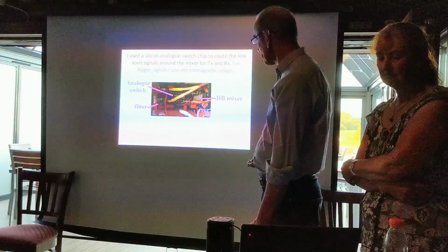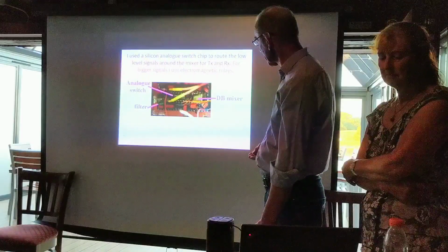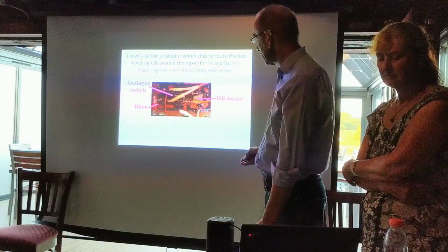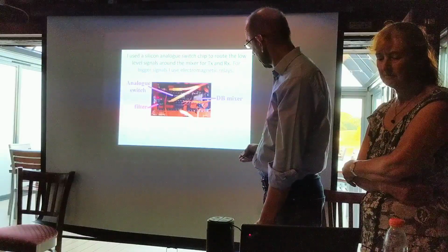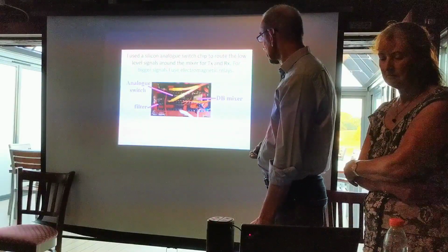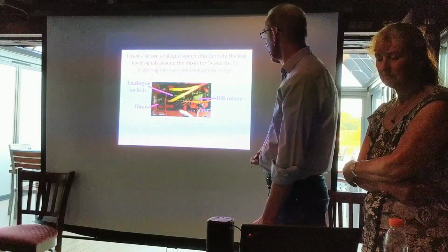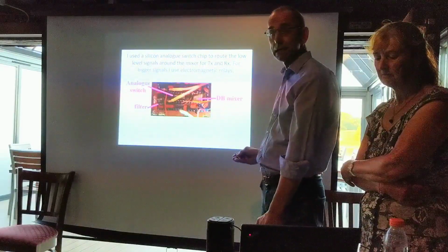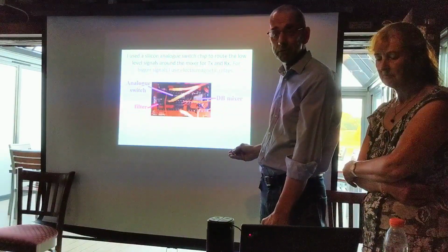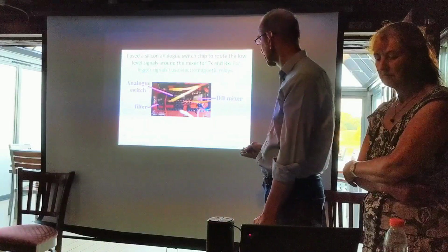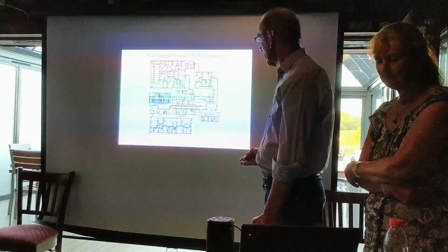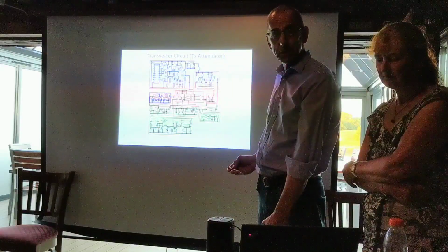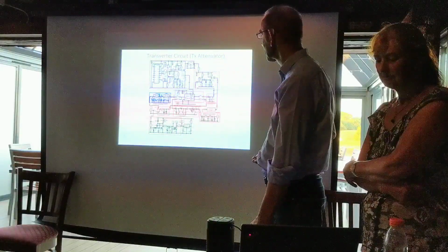And here it is. There's the analog switch, there's the double balance mixer, and there's the little filter circuit, and also a voltage regulator. For the bigger signals, like the output from the transceiver, I'm using relays, because obviously they're bomb-proof, they're not going to blow up if you put big signals into them. Right, and you'll also notice there are a lot of coax around that, because that's where all the switching happens and it goes off to all the different bits.